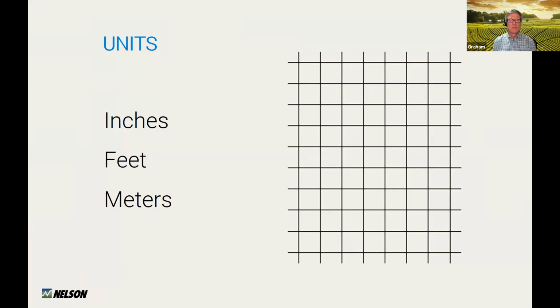As an example, I recently received an AutoCAD file that had originated in the metric world with survey equipment. And so the survey was done in meters. That was imported into AutoCAD, where the default units must have been left as inches. And so that was worked with, and then I received that file and imported it into IRRICAD.